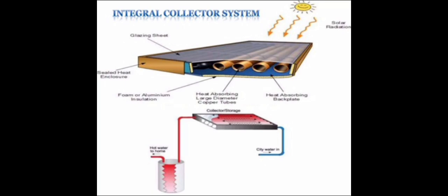The flat plate solar collectors are highly useful for low temperature heating. The main use of this technology is in residential buildings where the demand for hot water has large impact on energy bills. Commercial applications include car washes, military laundries, and eating establishments. Some advantages of flat plate collectors are it is easy to manufacture, it has low cost, it can collect both beam and diffuse radiation, permanently fixed, and it requires little maintenance.